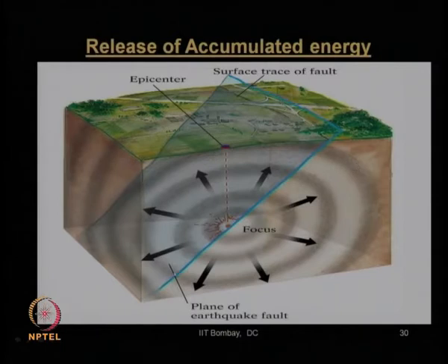So, this picture shows that we have to identify the plane of the earthquake fault, its depth, its projected or cross sectional area, and the trace on the ground surface is the surface trace of the fault.